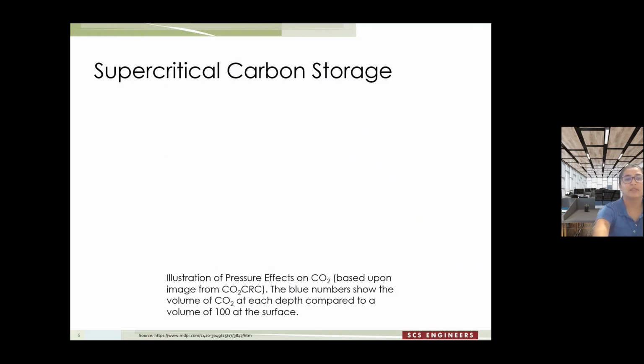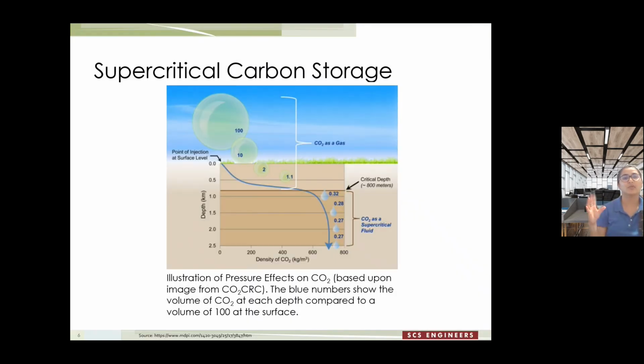So think of it this way. You have a room which is 100% carbon dioxide. And now you want to store that carbon dioxide in the geologic form. As you start injecting, the temperature and pressure increases. Once it hits that critical threshold, the volume of that gas starts decreasing, so much so that this whole room, which was filled with carbon dioxide, is now the size of a pebble. So the potential to store that carbon dioxide in the geologic formations is pretty huge when we store it as a supercritical fluid.